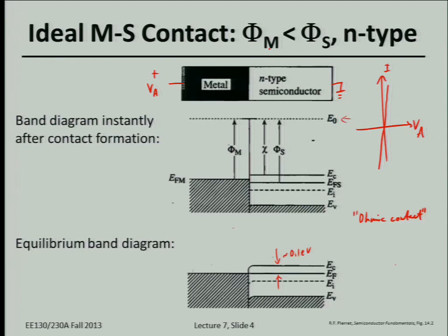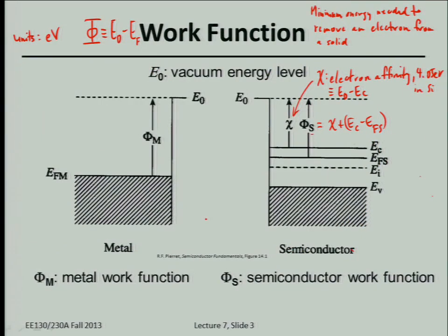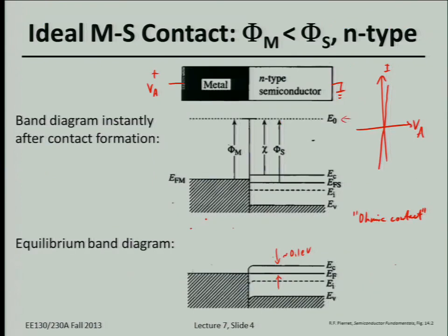That's right, the Fermi levels are equal, and the Schottky one is not equal. Well, the Fermi levels are always equal. The work function is not necessarily equal, right? That's a good question. One thing that was missing here also is the E naught. E naught is up here, like this. So the work function for the metal is still different than the work function for the semiconductor. We're not equilibrating the work functions, we're just compensating for the work functions by having a built-in voltage developed right in the semiconductor. Does that make sense? Okay, good question.